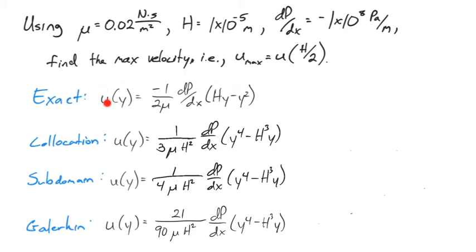All right, so here's our exact solution, our analytical solution. I purposely picked this assumed solution so it's got a similar form, but obviously it's the 4th power, not the 2nd power here. But it maintains that we can hit the boundary conditions: 0 at the bottom wall and 0 at h, the top wall, so 0 velocity at those locations.